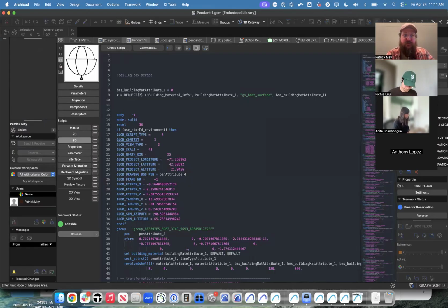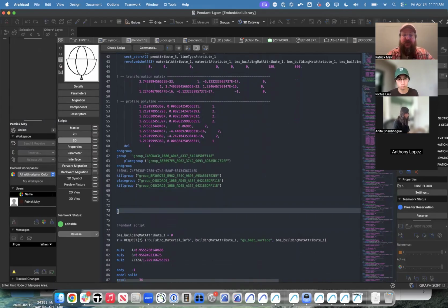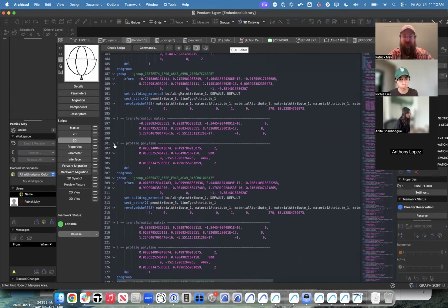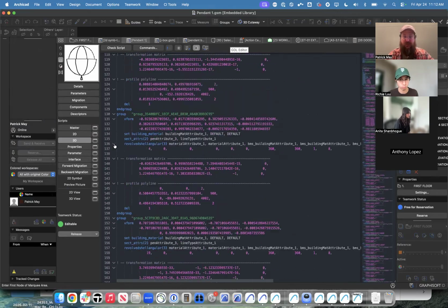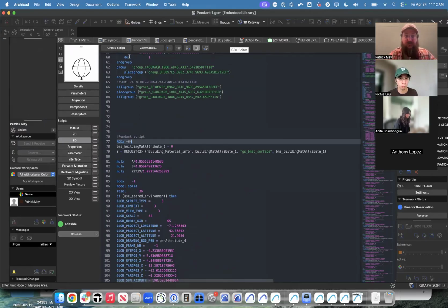Okay. Now under the 3D script, I create an add command. And everything after that add command is what's going to be affected. So that's why the box here is above the pendant here. This is the big script, that whole pendant geometry at the bottom. So here I'm going to put add Z negative HH. So it's going to shift that down HH. So there's the ceiling script at the top, the ceiling box, and here is the pendant.